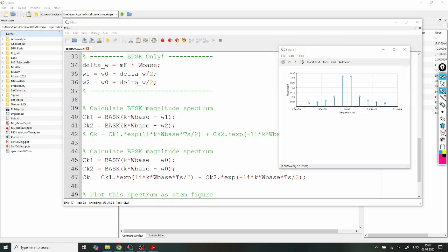Now, because the central value does not consume energy anymore, you can see that these other values actually even exceeded 0.25, well, 0.25, which was here, yes? So that energy went to other components which contain your information. And that is why this modulation type will in future show as the most robust and noise resistant, yes? Because all of the energy is given to information. And even more so, we use absolutely opposite signals with opposite phases. Yes, so that's also good.